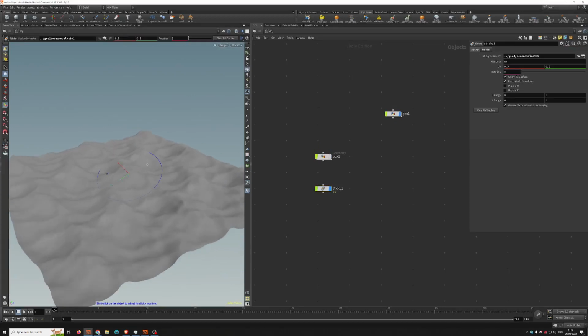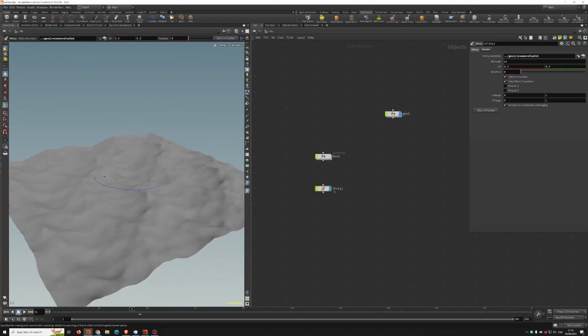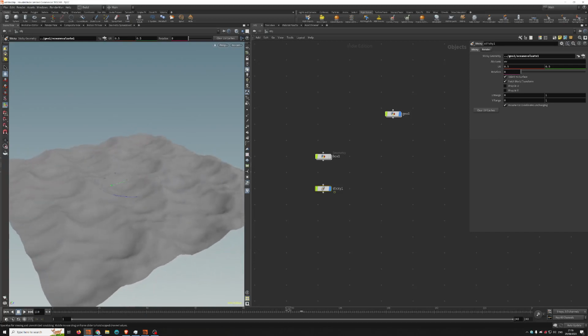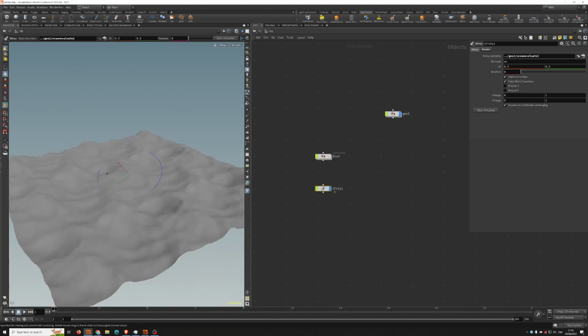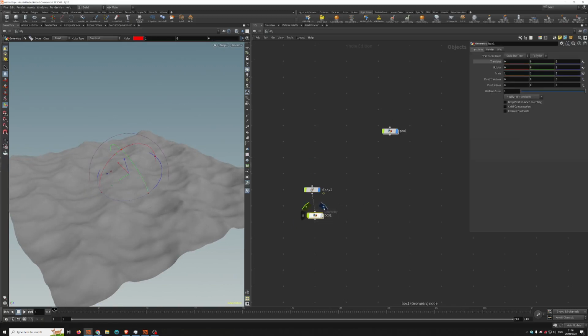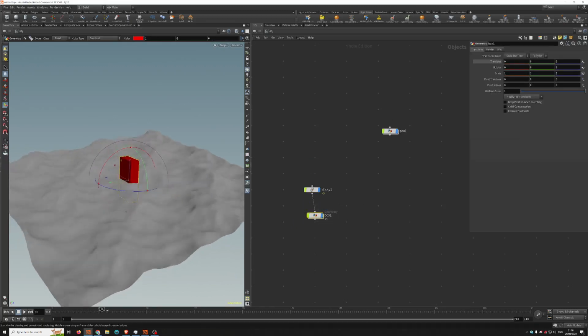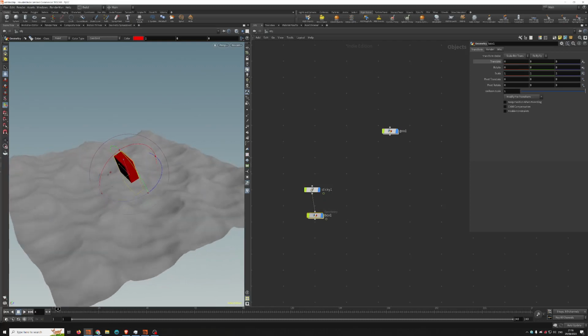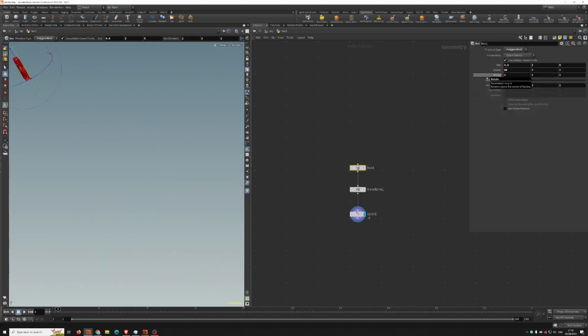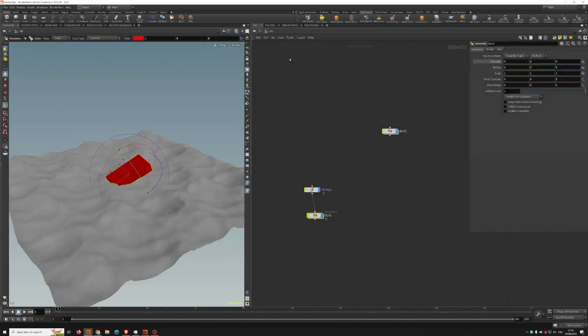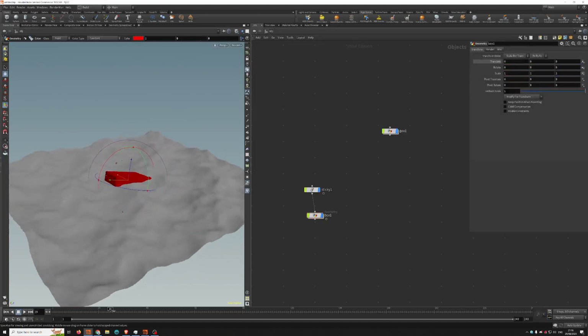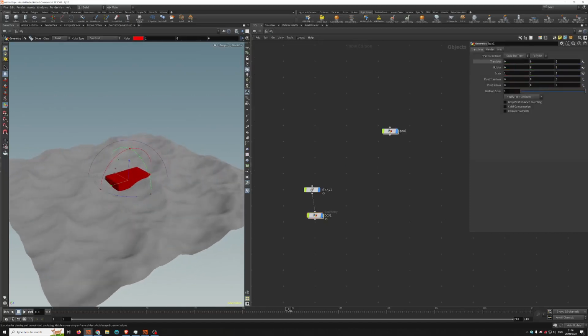You can see it puts some nodes. It was called the rivet in Maya. You can see it follows the movement of things. All you have to do is, this is the box and this is the sticky. All you have to do is put the stick on the box, as you can see, and now it will stick on it. Of course, we change the orientation. I want the rotation something like this, and now it will move accordingly, floating on the waves.